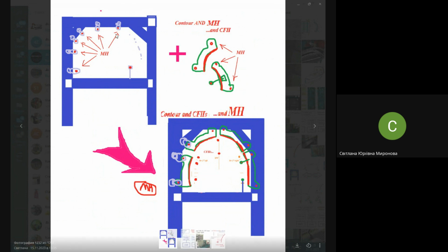And when, not if, but when you hang locators with respective holes on such a frame, such a skeleton, the system of locators inside gives you the proper contour and proper position of coordinate fixing holes. All the things are preliminarily measured. How exactly are they measured? Do recollect that it might be measured by an instrumental stand or a universal coordinate measuring table.